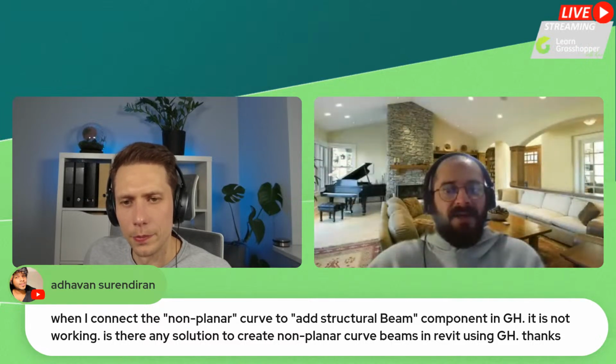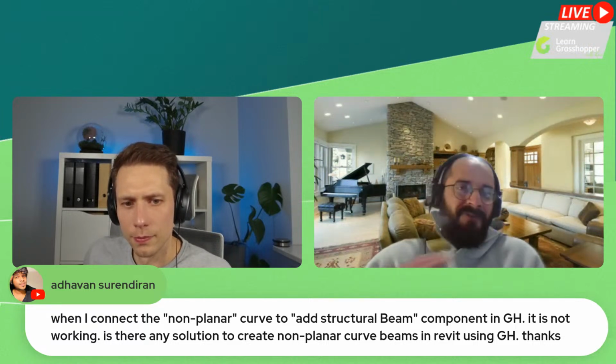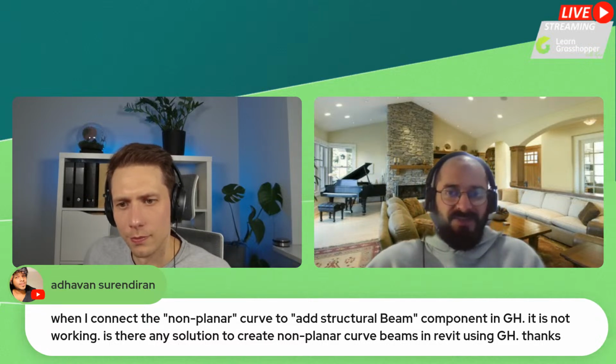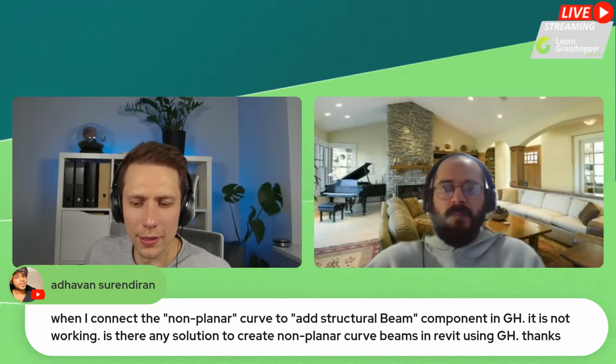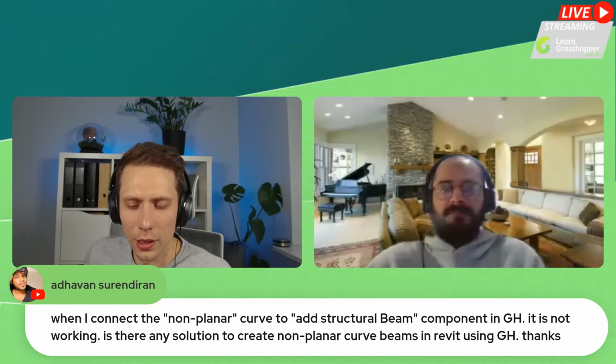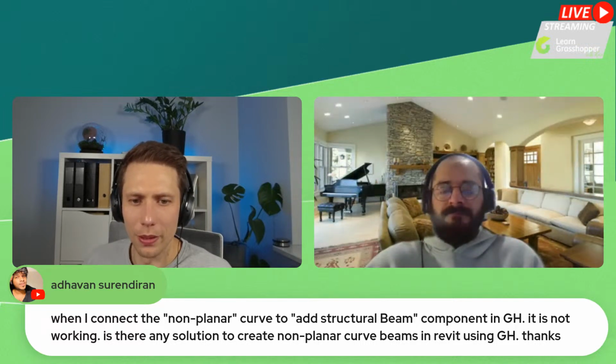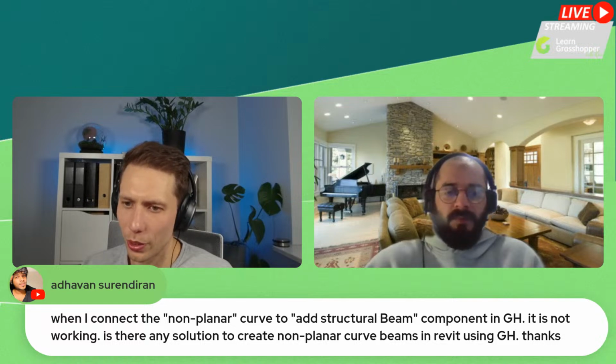And then when you insert those as a detail line, you will not have this planar problem or discontinuous issue. Or maybe when you are creating these lines, you have different planes. Maybe that one is in XY and you are creating in XZ, then you have to rotate this one. Yeah, always when importing some curved lines into Rhino, I always explode them and try to simplify them. So this is really a good recommendation.